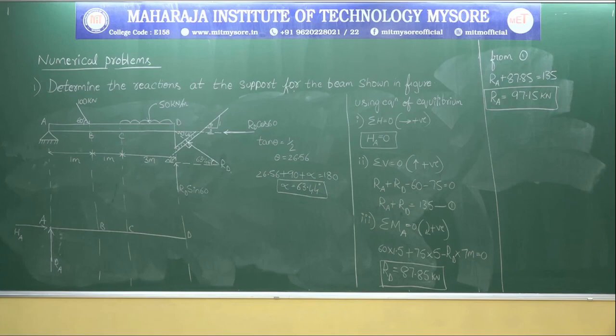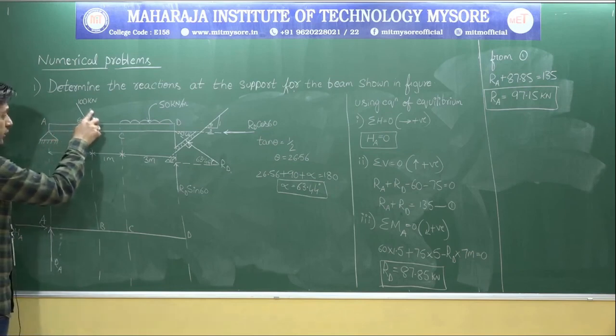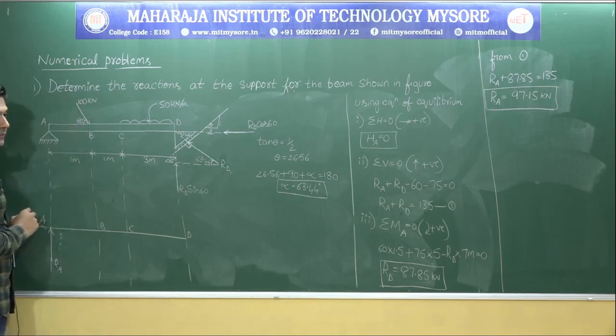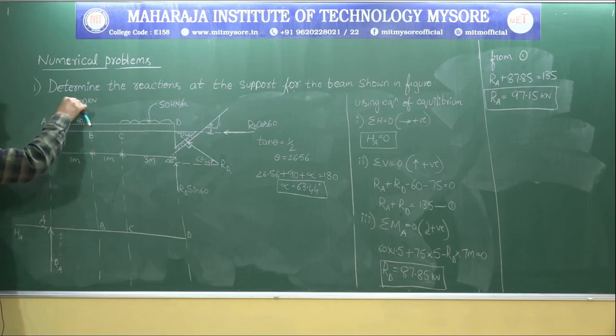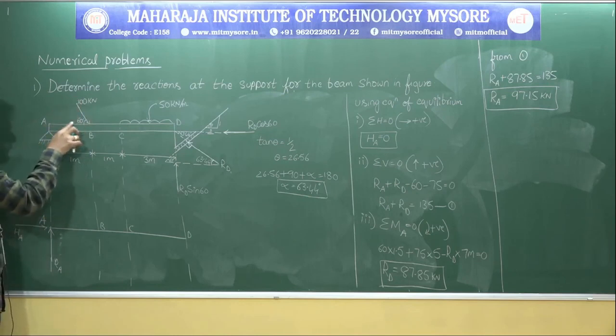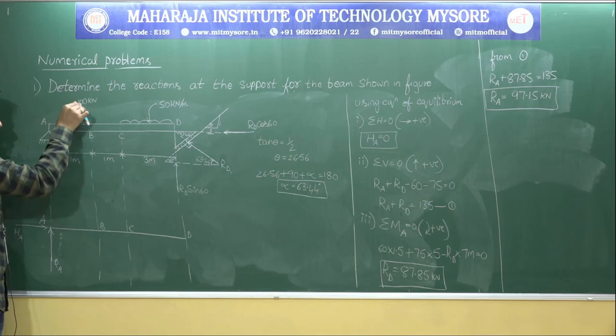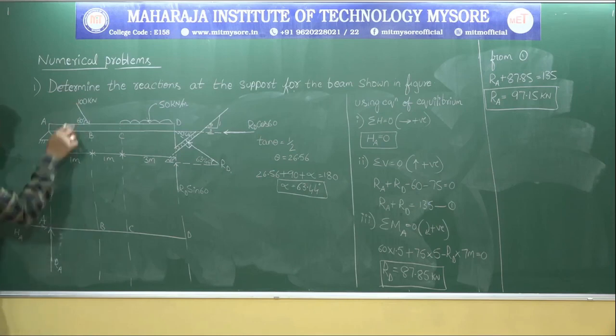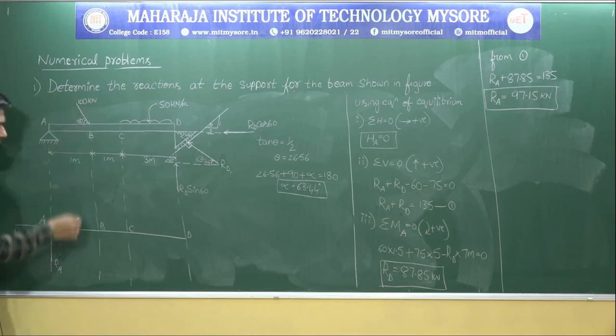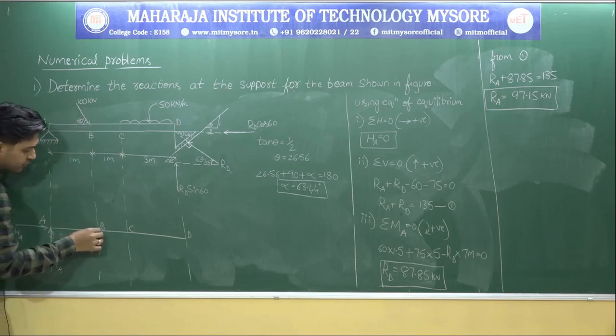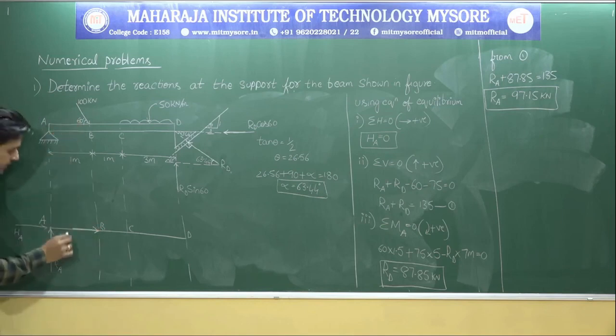Next, so here you are having an inclined force. I want you people to tell me now, this inclined force, with which line it is making an angle? Okay, so that will be cos. If I resolve this towards the horizontal direction and the force is acting towards the point, therefore its resolution should also act towards the point. So this will become 100 cos 60.